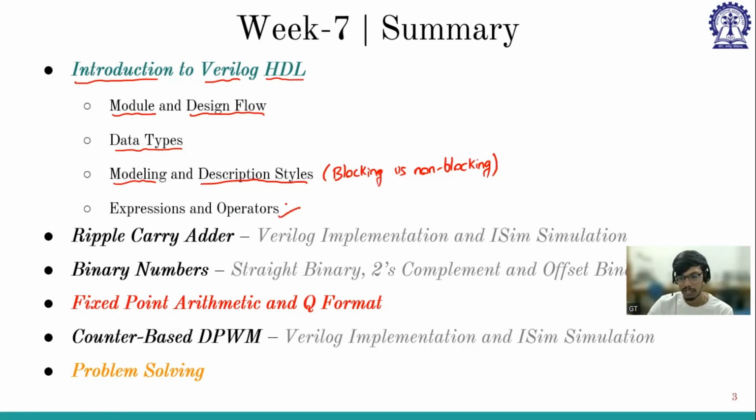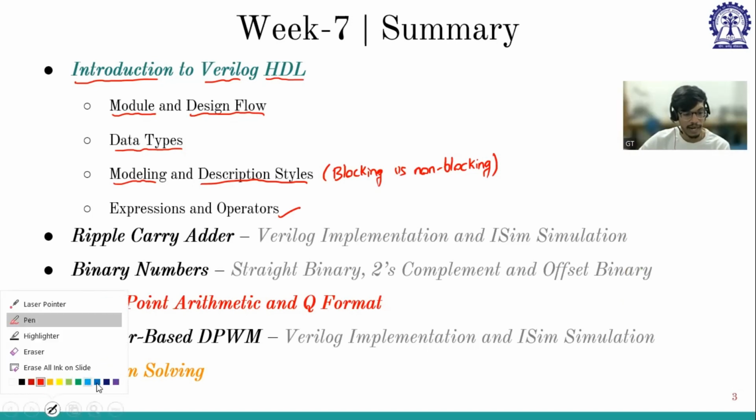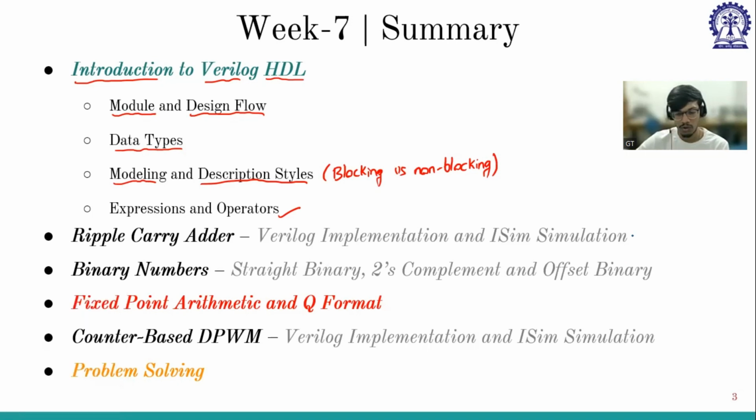Then we discussed the ripple carry adder. Before we write any code, we have to actually design it, so we discussed the top-down approach. In the top-down design approach of the ripple carry adder, we realized the ripple carry adder using full adders, then the full adder using half adders, and then the half adder using gates. Then using the same logic, we implemented the Verilog.